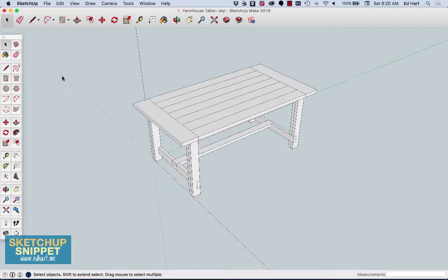What that will do is help SketchUp anticipate the things that you want to do, so that when you're trying to grab an object like the corner of, say, this table board, with the move tool, it will snap to the corners or to the end points, and it'll anticipate what you want to do. And as you drag it around, as it relates to the origin, you'll be able to snap to the origin. So I like to make sure that those things are set, and they usually are by default, but I just want to make you aware of them.